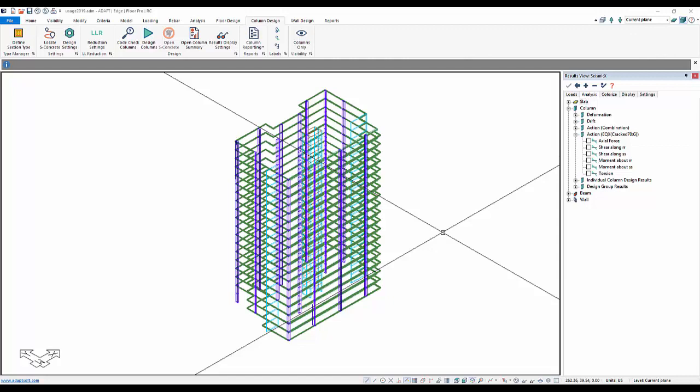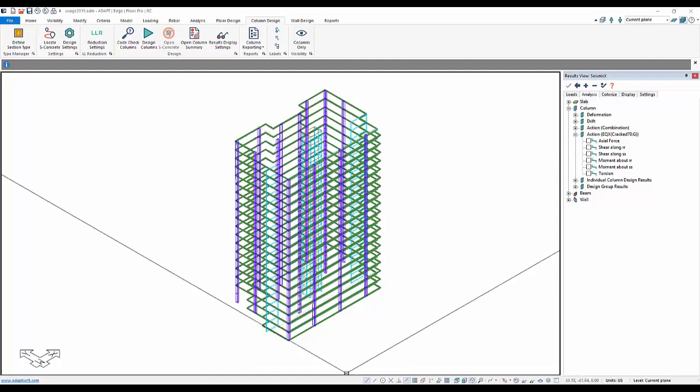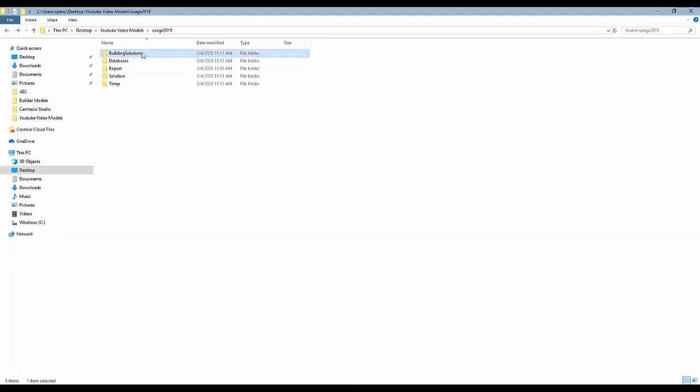If I then run cracked 50, that would replace that solution, and those solutions are actually stored in your model file under the building solution data. So this is the latest building solution stored here, and these ADO files contain different displacements, reactions, frame forces, etc. for the combinations or the load cases that have been solved under that particular usage case.